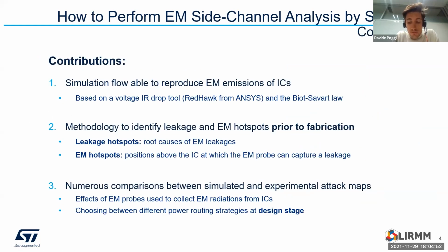So today I would like to share with you 3 contributions. The first one is the development of a simulation flow able to emulate the magnetic field radiated by an entire IC. This is a flow based on a commercial IR drop tool, RedHawk from the ANSYS company, and on the use of the Biot-Savart law to model the electromagnetic phenomena that we observe on silicon.